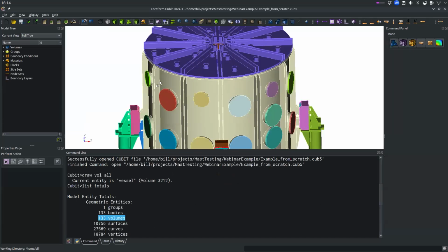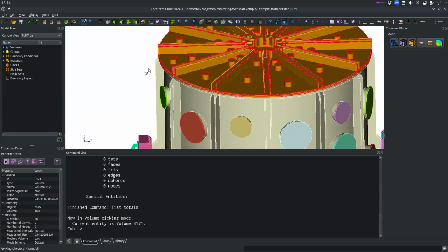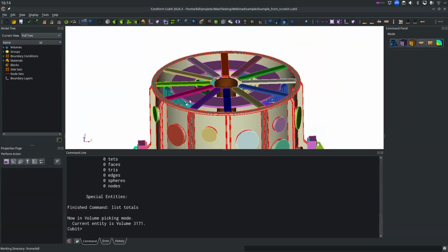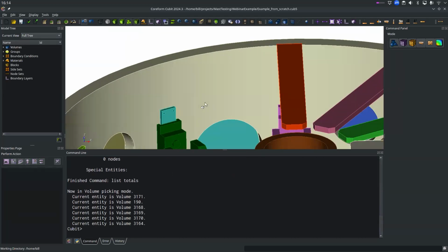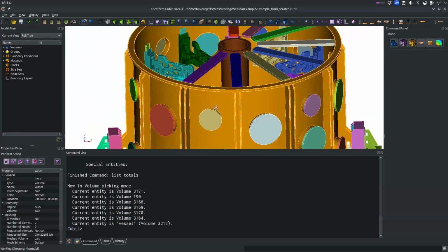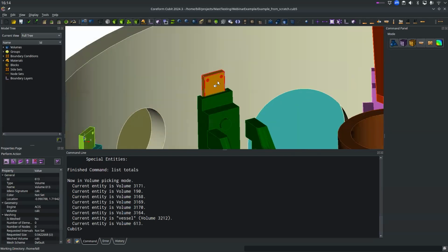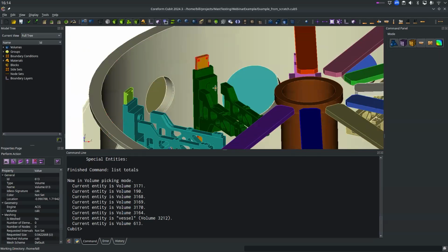So what might we want to group together for imprinting and merging? Let's get rid of the top of the baked bean can, which is this tokamak, and see what structurally needs to be stuck together. A great start is this main vacuum vessel body, and these supports that go around the vacuum vessel body radially, and they help support these radial arms, which in turn support many other components. But let's just focus on these for now.